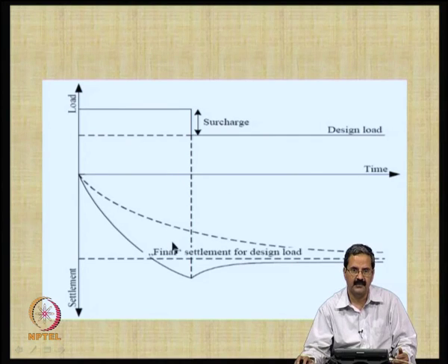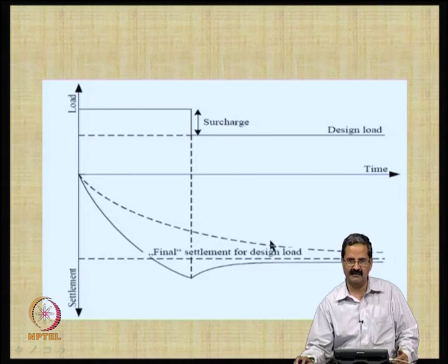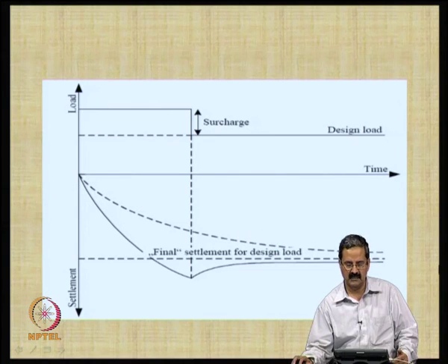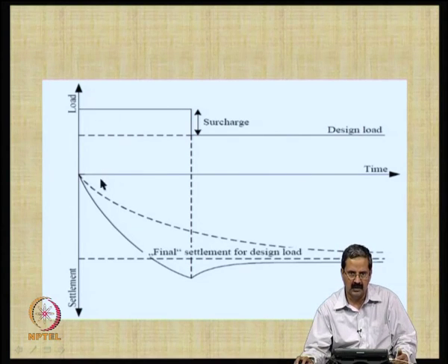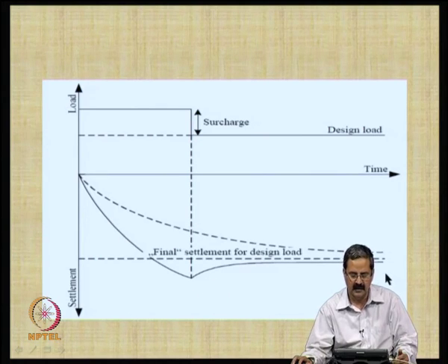To reach that settlement level, consolidation in a regular manner takes very long time, maybe about 4 or 5 years, but with this you are able to preempt the whole consolidation, and then even if there is a release, it is all right. You are able to achieve that settlement in a shorter time. That is what we want.